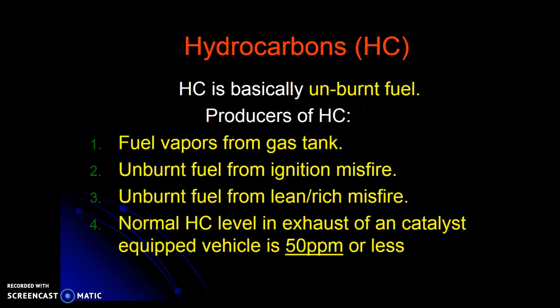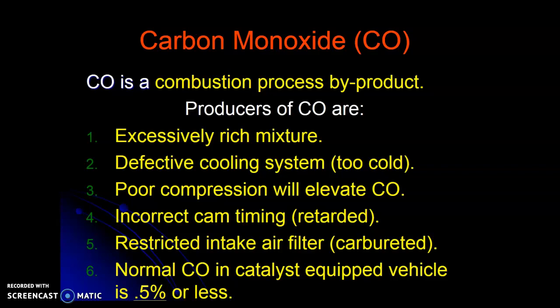So hydrocarbons, again, like I mentioned, is your unburnt fuel. Fuel vapors from the gas tank, unburnt fuel from ignition misfire, unburnt fuel from lean-rich misfire, etc. Carbon monoxide is that byproduct: either rich mixture, defective cooling system, poor compression gives you that incomplete burn. Incorrect cam timing, retarded cam timing, restricted intake air filter. Normal CO in catalyst-equipped vehicles is 0.5 or less. This is for diagnostic purposes. But basically, if you're seeing CO, then you're either rich or something's causing an incomplete burn.